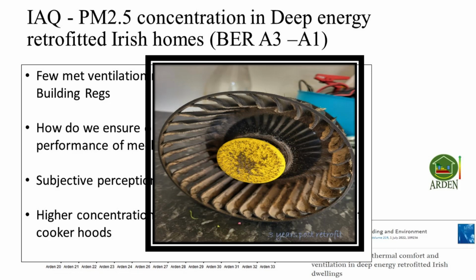This is the addition of fan in the ventilation system, and once the system was cleaned, yes, the system went back to complying with what it should be in terms of the airflow requirements in Part F. So that's just a question again we need to consider: how do we consider the ongoing maintenance and performance of mechanical ventilation systems, because that's the way forward.